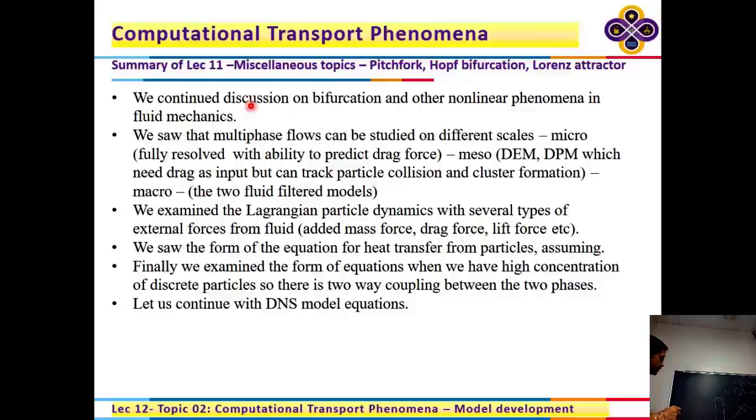The other thing you can do is provide a good initial guess for those velocities. What does it need? It needs some sort of an oscillatory profile like this. The default initial guess is VR is 0, V theta is 0, V Z is 0.